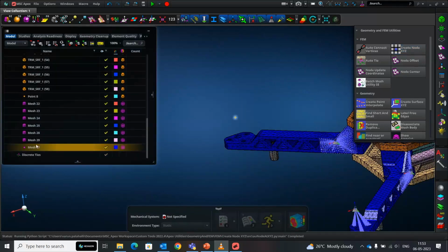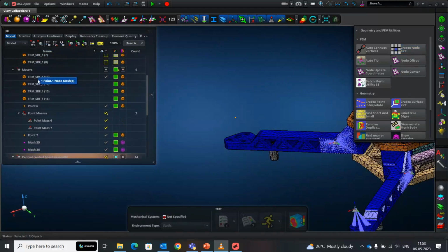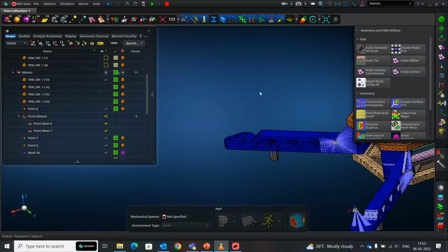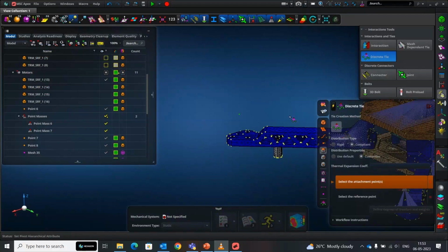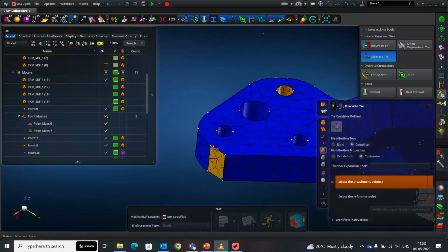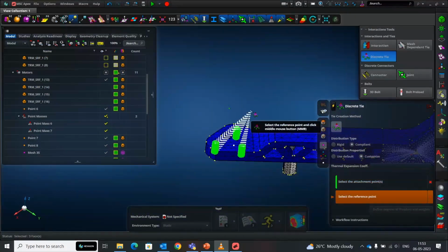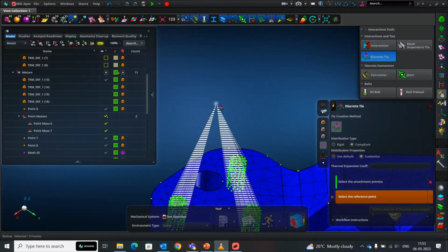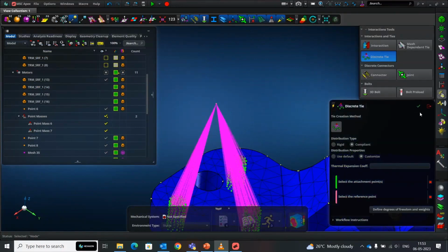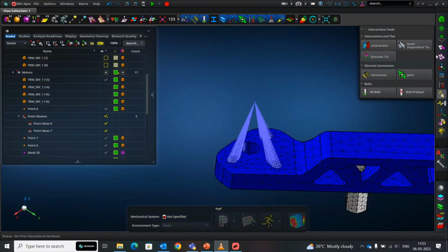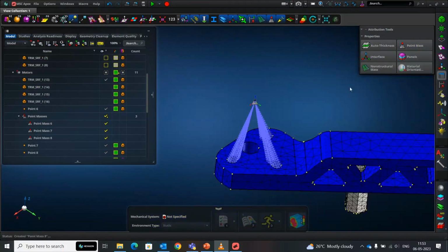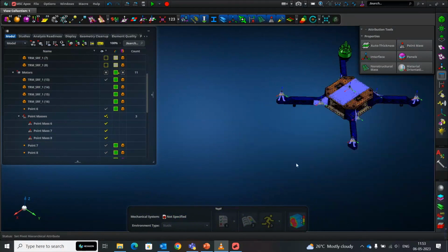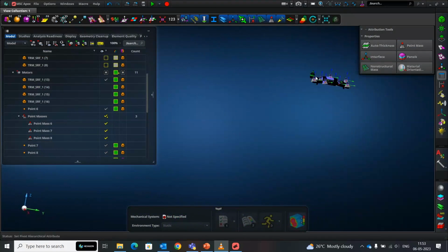So I hide the actual structure itself. What you can see here is I don't really need to mesh components which are bought out, like motors, ESCs, controller boards or battery packs. All that is of interest is what I have designed, which is my airframe. So it becomes a lot easier and a lot less tedious, and also computationally a lot more advantageous. One final motor is remaining.